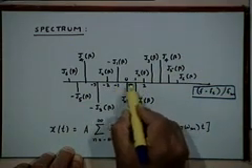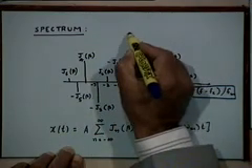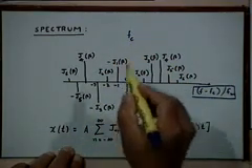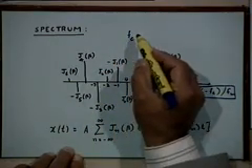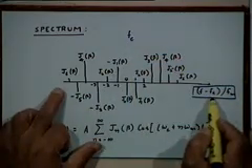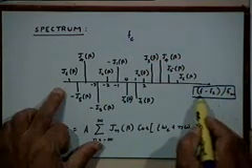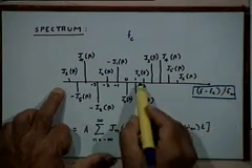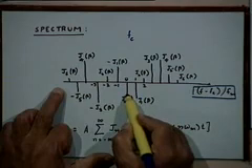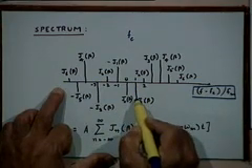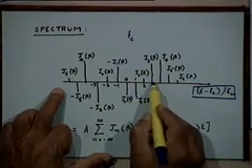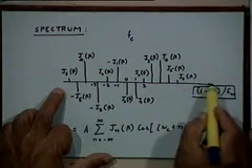I have written 0 and minus 0, 1 and minus 1 here, but remember that the point 0 actually denotes the frequency Fc, because I have normalized it by subtracting the value of Fc from F. So this denotes the component at the carrier frequency, this denotes the component at Fc plus Fm, this denotes the component at Fc plus 2Fm, Fc plus 3Fm and so on and so forth.